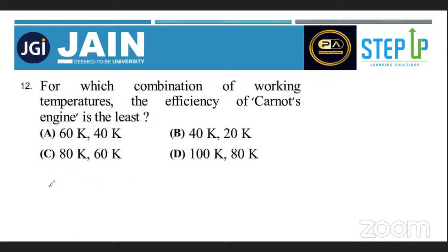So Carnot engine efficiency is given by eta equals 1 minus T lower temperature upon T higher temperature. Okay. Efficiency is 0.2. 0.2 efficiency will be in percentage 20%. Yeah, the value will be 0.2. Correct. Yeah, Komal also has the answer as D.